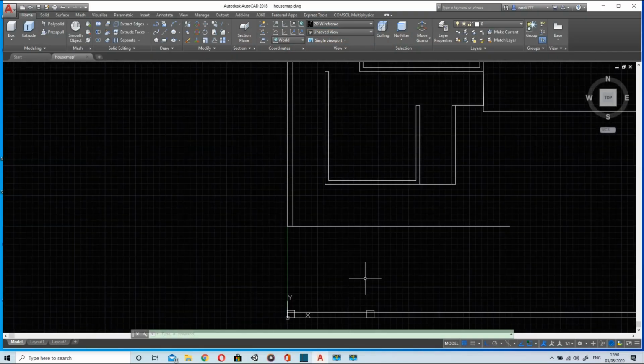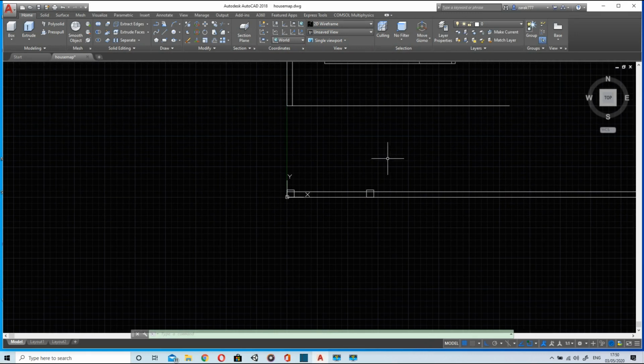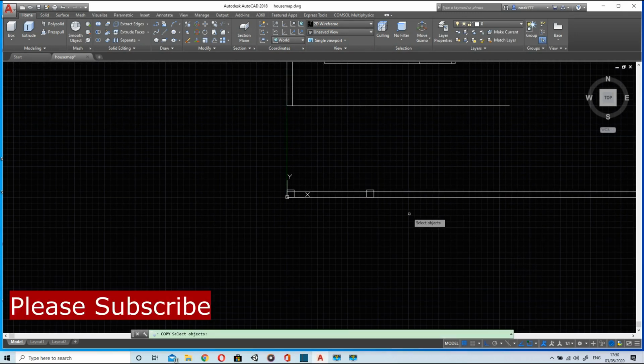As we discussed earlier, the layout was complete. Now we will place pillars on the drawing. Just copy this pillar to move it 10 feet 11 inches. We'll use the copy command. Hope you know how to use it. It is very easy. Select the object, enter, then pick the point from which you want to move it and direct your mouse in that direction, then enter the distance and press enter again.